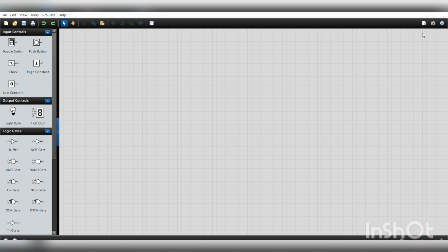An encoder generally gets 2 power n input lines which it encodes into n output lines. Let us take an example of a circuit containing 8 input lines which is encoded into 3 output lines, since 2 power 3 is 8. Now we are going to discuss the implementation of a 2 to 4 decoder and a 4 to 2 encoder. So let us see the implementation of the 4 to 2 encoder first.